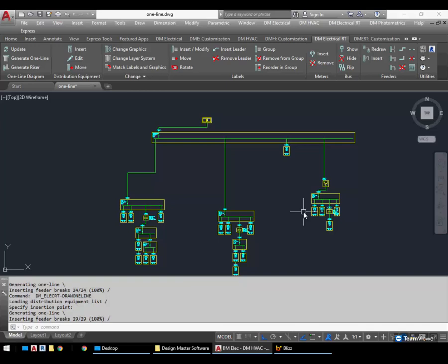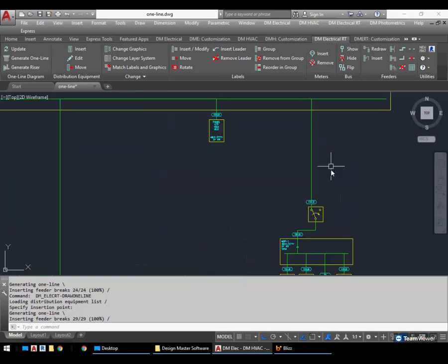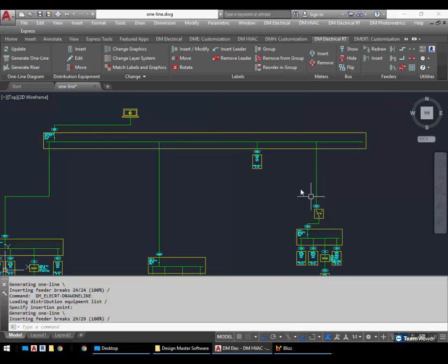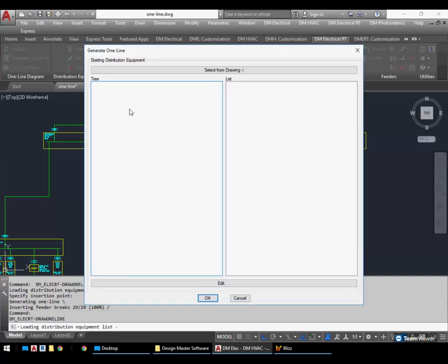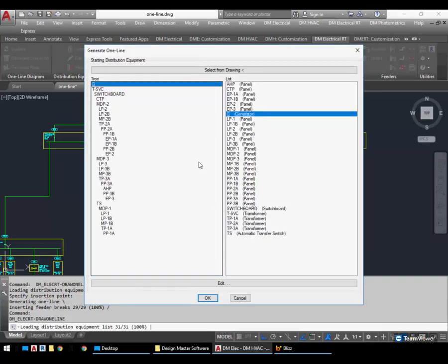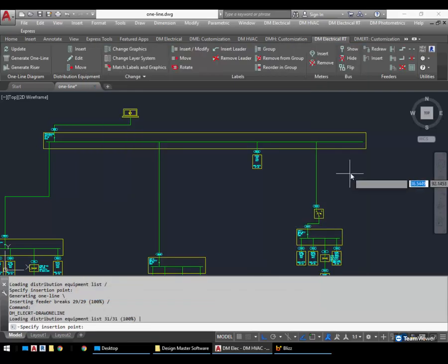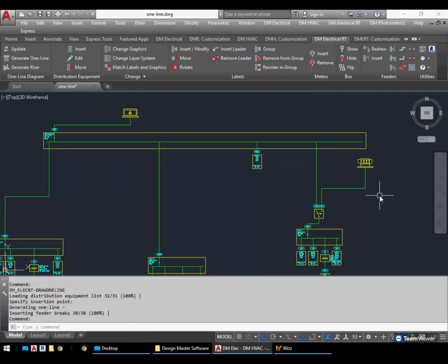That's also how you generate for a transfer switch. I have this transfer switch here. We did the main connection to it. We also have the emergency power coming from the generator. There's not a whole lot else on that branch, but if you generate and start at the generator at this point, again, it leaves everything where it is, and adds that one generator and the feeder. So that's how you do a transfer switch as well. You do the one side and then you do the other, and it'll make all the connections for you.